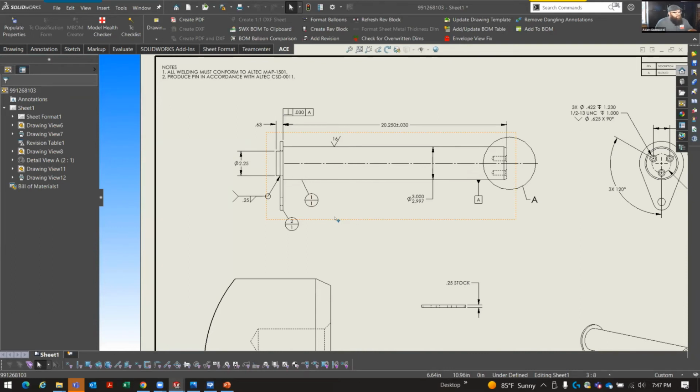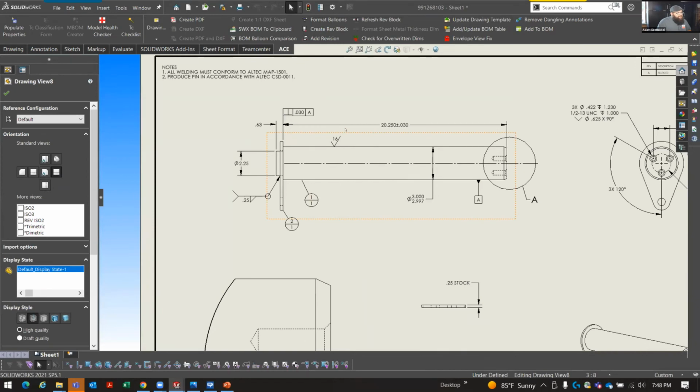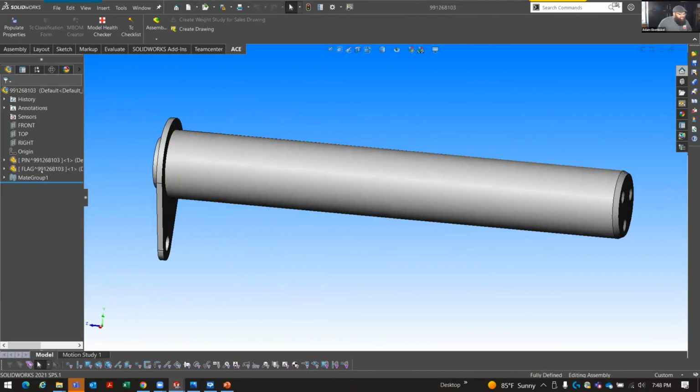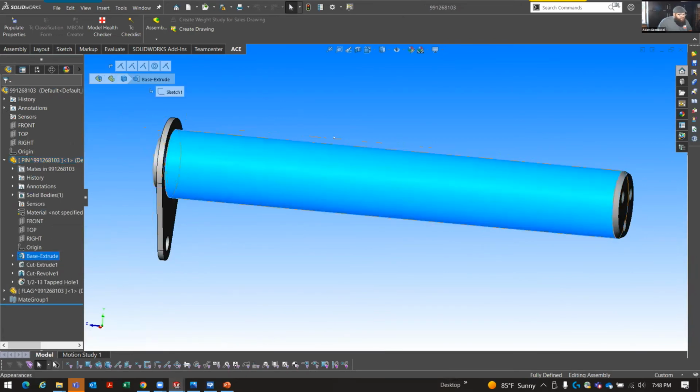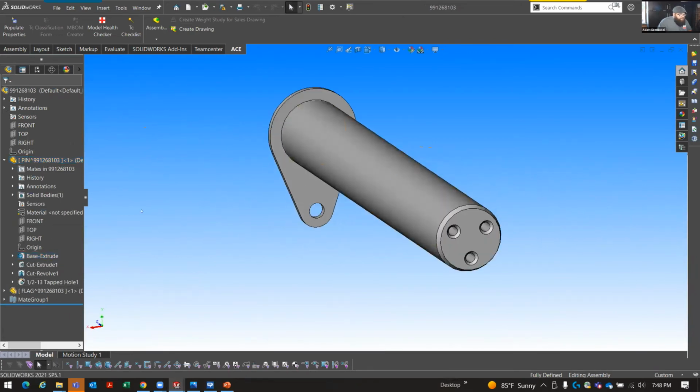I mean, you think this looks pretty simple to machine, right? Yeah. But if I come in here and we'll do some little in context cutting, because this is two pieces that are internally saved, which is terrible. Don't do that. Do not do internal virtual parts. Please don't. I hear laughing. Sounds like you've been down that road. Please don't.